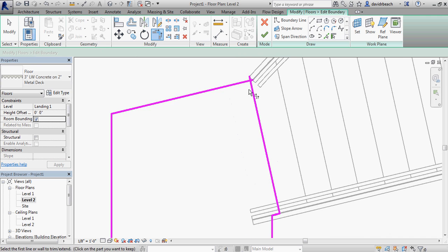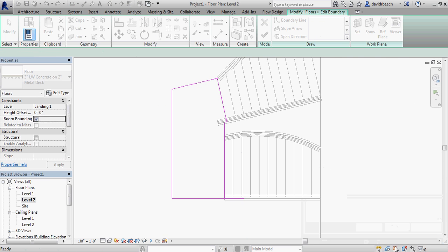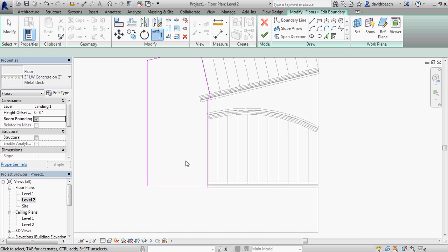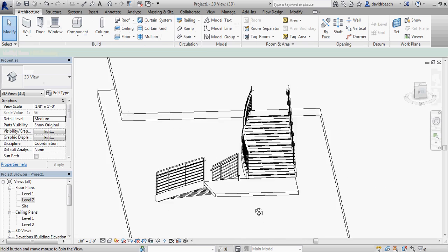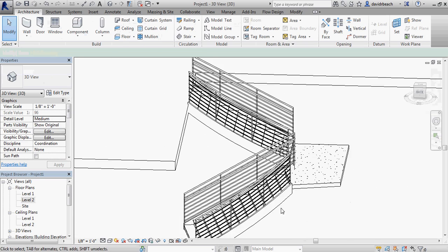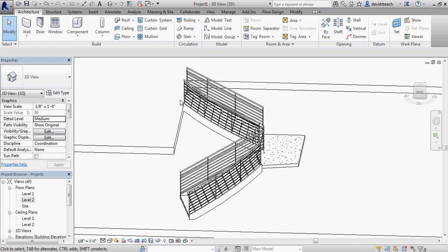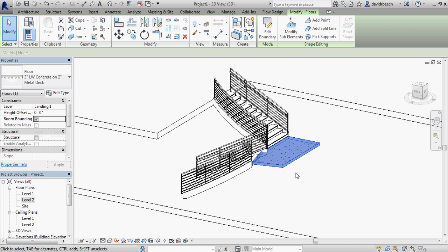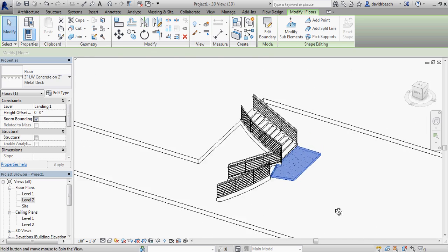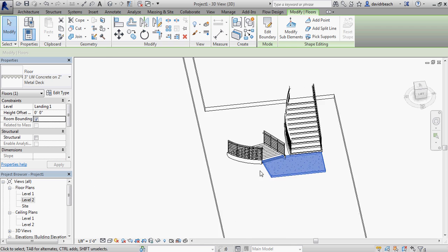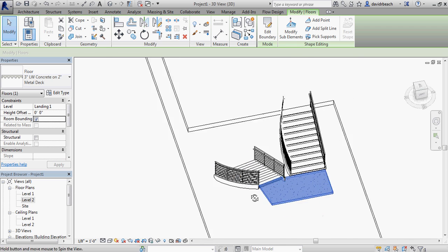It's probably more complicated for the quality of design than it should be. In other words, the design's pretty lousy. But it'll give you the idea that you can start making these custom shapes really easily, especially in terms of working with something that's stair to landing, landing to level, as a method. And obviously I need to do handrails around that landing, something pretty easy to do. And again, the things to watch for: handrail extensions, making sure that your stair doesn't get more narrow in terms of what happens at the top to the bottom as you're building these sort of custom shaped stairs.